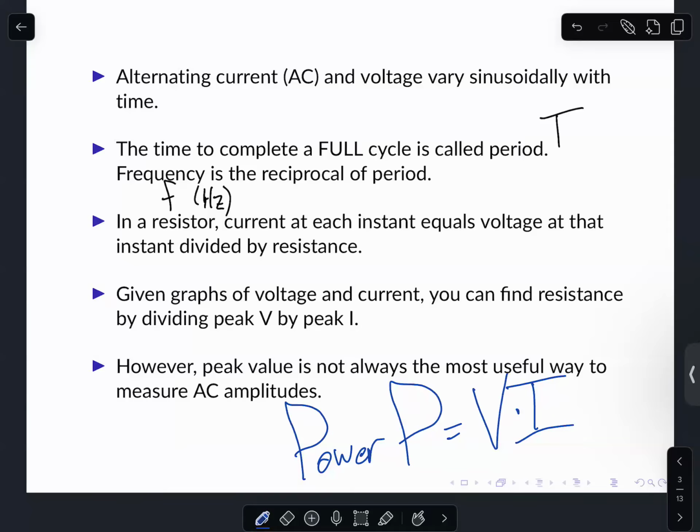Well, when electricity is really being pushed by the sine wave of AC, at the peak, there's a big voltage, there's a big current, there's a lot of wattage. But what about when the sine wave cycle goes through its middle, when there's temporarily, for that instant, 0 volts, 0 amps flows in at least a resistor? Is there any power being generated? Is any energy being transformed, transferred, traveling? No. When the AC signal goes through 0, there's nothing.